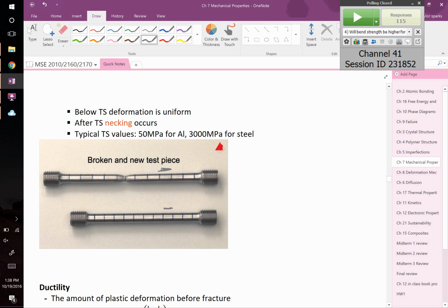But after the tensile stress, the ultimate tensile stress, all of a sudden you get a region where something funny is going on. This thing bends in. It forms little necks, right? So that's necking, where you have a region of extreme local plastic deformation. There's general plastic deformation all over this thing, but you get a region where locally it's doing something even more severe. So this cross-sectional area is smaller than we started. Therefore, if it got smaller, the actual stress is quite a bit larger there.